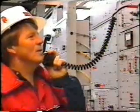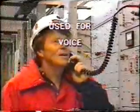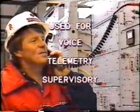This also allows the channel to be used for other forms of communication, such as voice, telemetry, or supervisory information, all in addition to its role in protection. Of course, the protection scheme always takes precedence and will interrupt other transmissions when required for protective relaying. And we'll be talking more about these additional channels in the next segment.